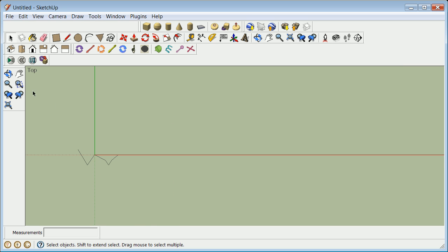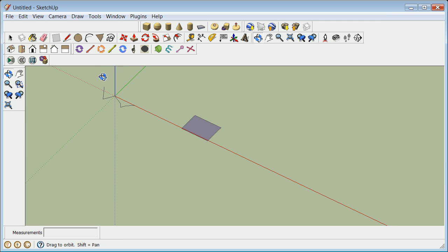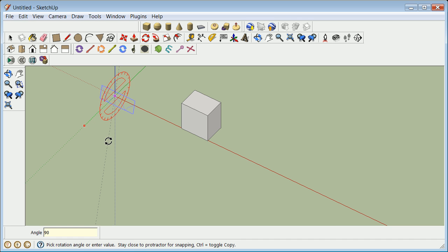Alright, so how do we do that? Well, the one kicker in this program, again I'm going to point out, I'm showing you this. This is pretty easy. It's going to be easier to do by matrix transformations. I'm going to make a little, more or less, a world where I'm hitting P for push here, where I've got my three axes. Because what I want to do is rotate about the x-axis. I do it this way. I select my thing. I grab my rotation tool. I think R is the key, and I grab the face and hold the shift key. I go to my rotation point, click here, and I go down 90 degrees.